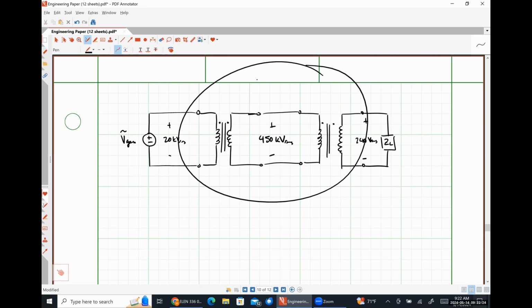They have a disconnect. Absolutely. Yep. Very small. Anything can fail. But so, yeah, when you hook up a generator, like when you have a whole home generator or a permanent generator for your house, it has an automatic disconnect switch. So that's what effectively physically switches your power from being connected to the grid to being connected to your generator. There are two isolated things. And it has to switch back to disconnect your generator back to the grid. So it automatically has that switching in it.